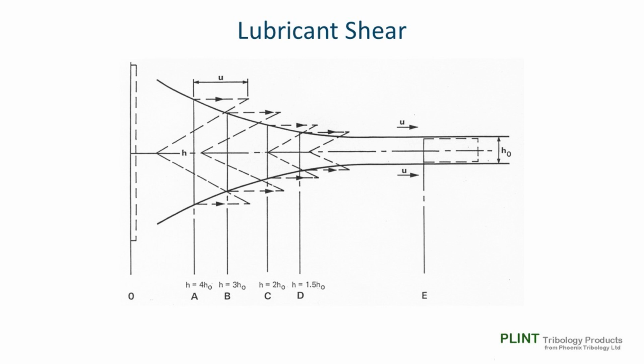It is perhaps no surprise that we have a lubricant shear stability test, the KRL test, which involves running a loaded taper roller bearing under load immersed in a small volume of test oil for a number of hours. This is followed by measurement of the kinematic viscosity of the lubricant.